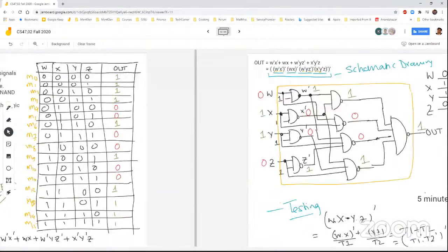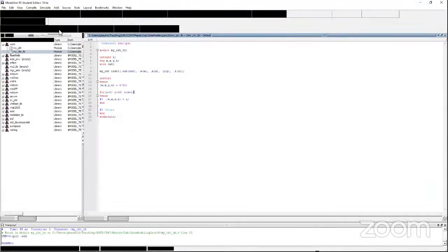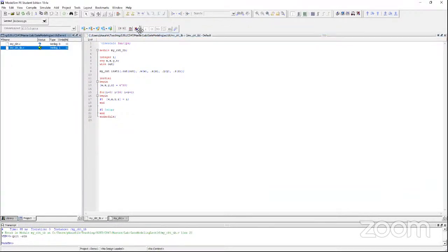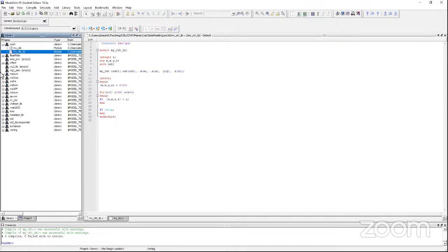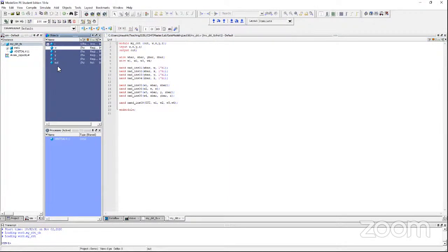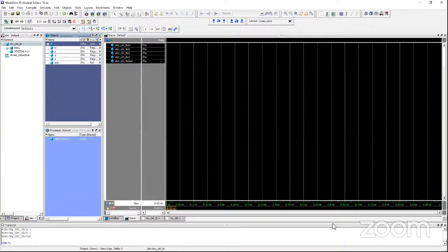of all these combinations, like 0001 to that 16 combinations. So it is doing that part, and then we can actually compile my project. Let's just make sure we compile it. This compilation is okay, and then we load the whole test environment, and let's throw it in the waveform viewing.